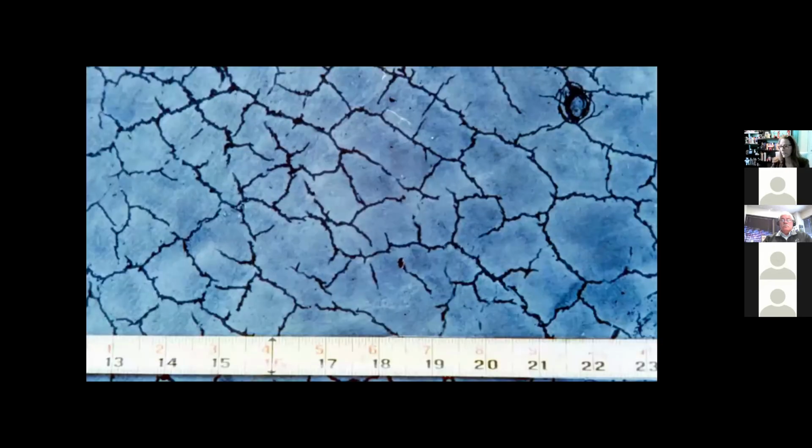This is an example of concrete under a microscope. Ignore the squiggle up on the screen, although they're identifying a certain piece of aggregate. But instead of this being crazing, what you see is that the cracks have slightly opened up into a V notch. And what that means is that the concrete is now checked, is a term we use. It's more common in the paving industry, but checking, to me, is a bigger issue because this could imply more of a durability issue for scale. This means it's opened up, it's going to allow things in. So that's my only concern with crazing as well, is would it open up?